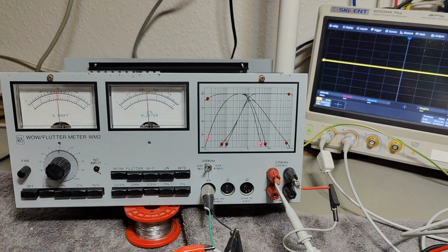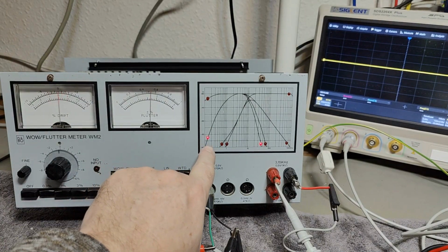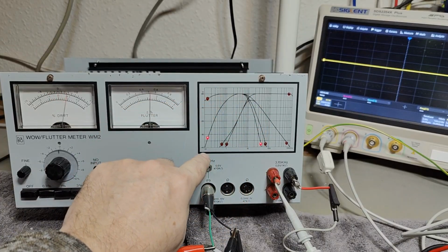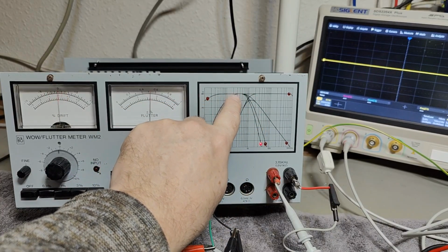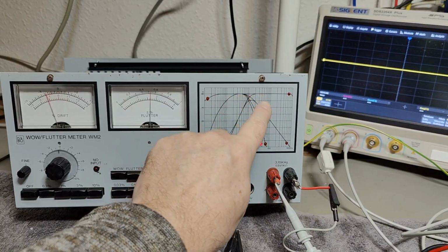But here's the flutter. So if I change the frequency deviation, that is 5, 4, 3, 2. So this is how much it is deviating. And if I go up to the frequency of modulation, so if I change the frequency there to 4, 3, then you see it goes slower. And I'm still in the frequency range of this peak. See, this is 1 hertz to 3 hertz is where this peak is.